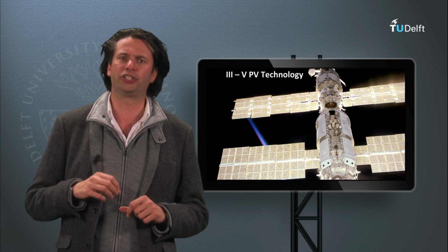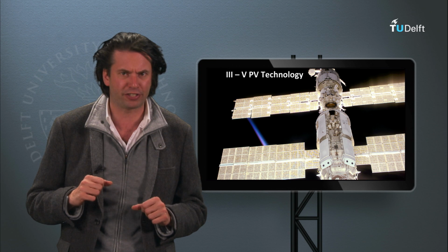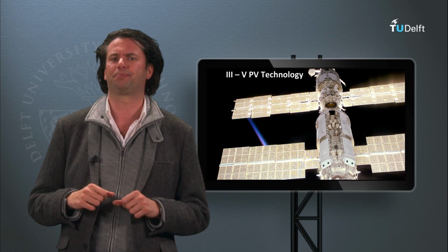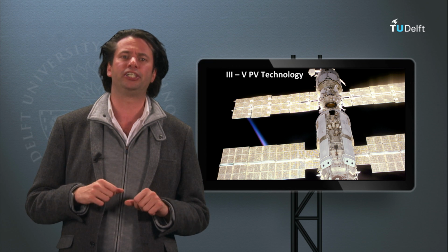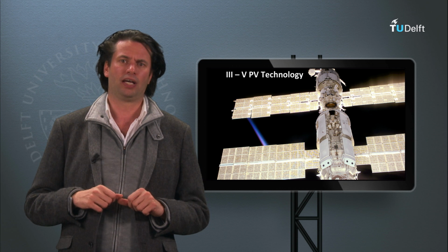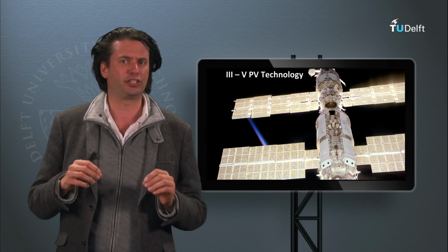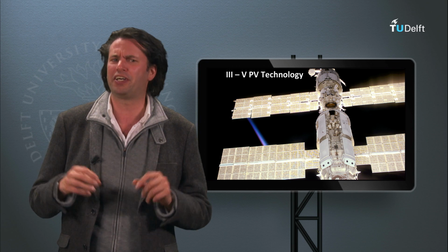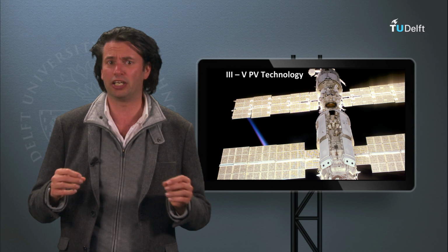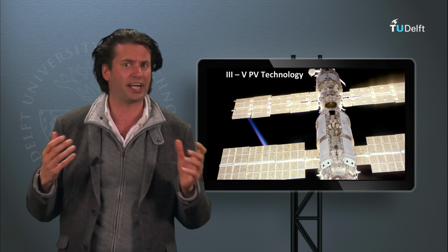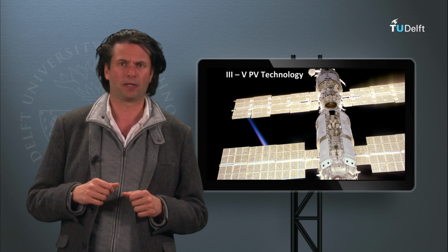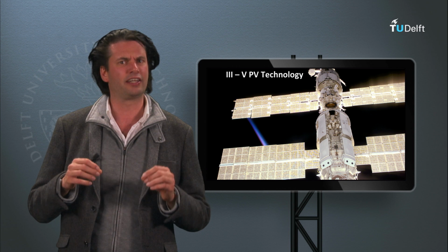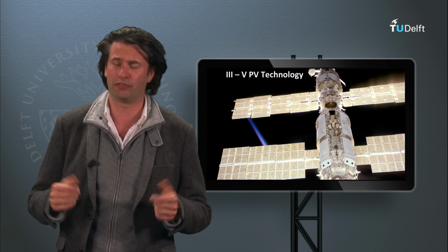This is the solar cell technology which results in the highest conversion efficiencies under both one-sun standard test conditions and concentrated sun conditions. It is mainly used in space technology and in concentrated technology. As some concepts use crystalline germanium and gallium arsenide wafer as substrate, it might not be a real thin film PV technology, like thin film silicon, cadmium telluride, CIGS or organics, which will be discussed later this course. However, the 3-5 based absorber layers itself can be considered as thin in reference to the crystalline silicon wafers.